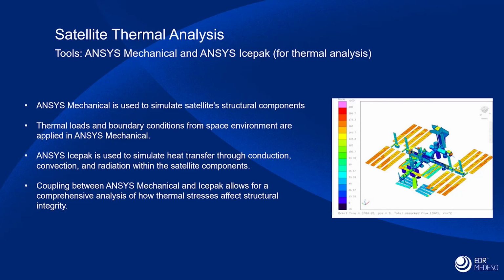Now, this materials data is available within materials databases within the Ansys suite. There is another product called Granta, which is a very full-featured and rich source of materials data. Or you may actually have your own bespoke properties, and ultimately you can input these, so things like your thermal expansion coefficients or your Young's modulus or Poisson's ratio of your materials.